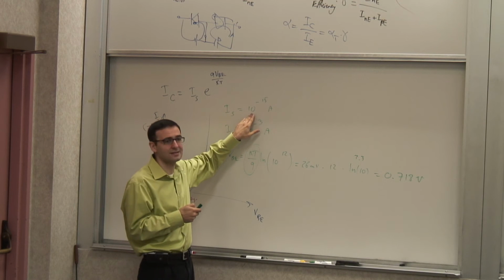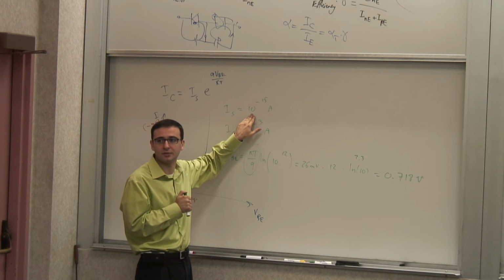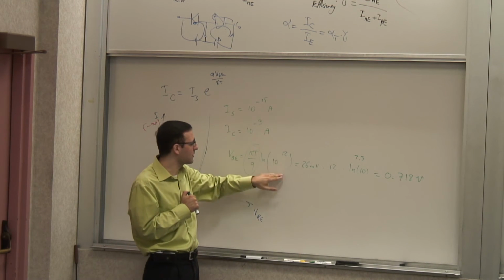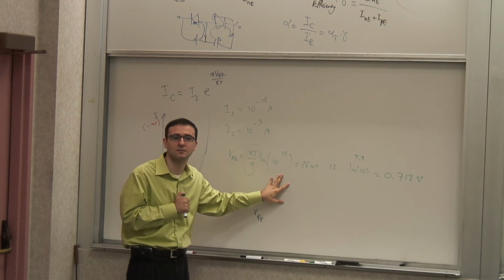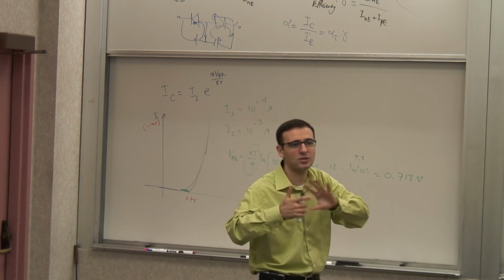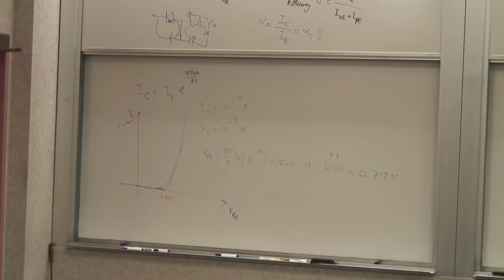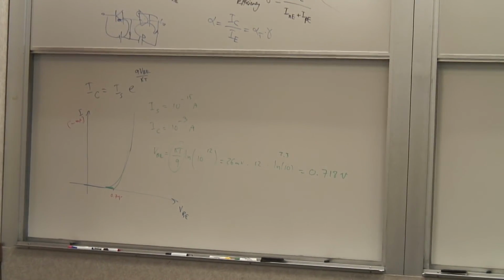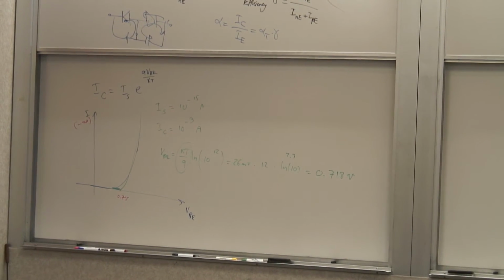So it's not going to be next to the 10 to the minus 11, 10 to the minus 12. And as a result, this number is smaller for a given current level. Now, milliamps are the typical current levels that we deal with, milliamps and hundreds of microamps, in small signal electronics.